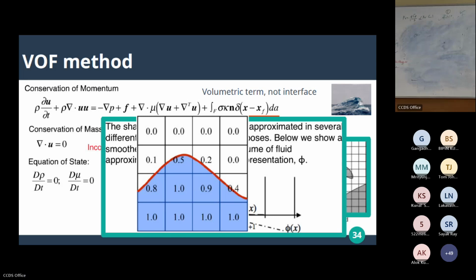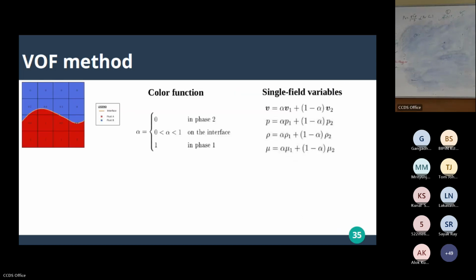Second thing, by any means, till now in OpenFOAM, completely successful interface capturing is not possible. You always have better and better approaches, but a complete solution is not possible. If one can do that, they will be in a position to write the complete velocity field as the alpha value multiplied by the liquid velocity plus 1 minus alpha multiplied by the gas velocity.